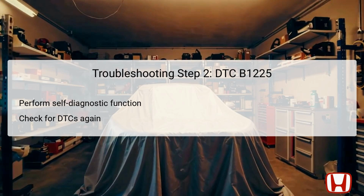On the other hand, if no DTCs are indicated, this may suggest an intermittent failure, warranting a thorough inspection for loose wires or poor connections, which could also translate into similar symptoms affecting the climate control system. Having confirmed the presence of DTC B1225, the next step involves turning the ignition switch back to the lock 0 position to safely access the in-car temperature sensor.